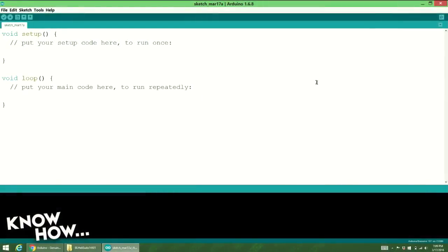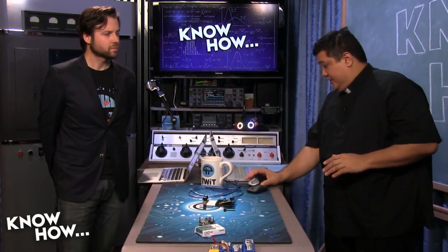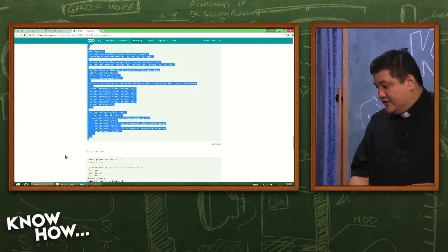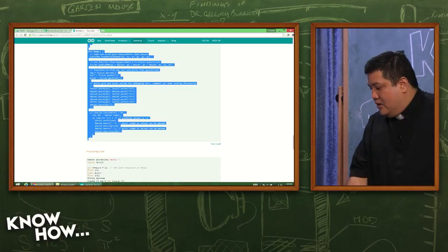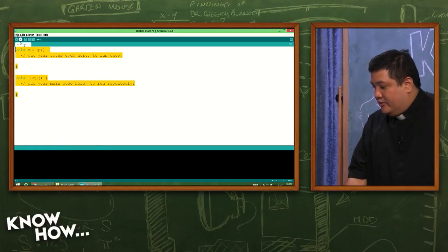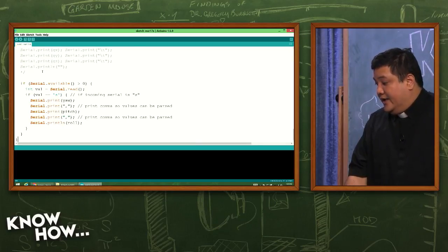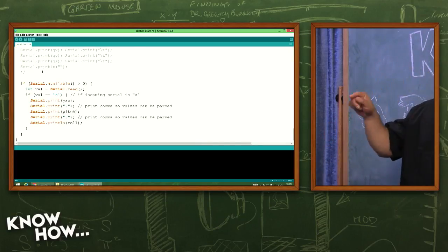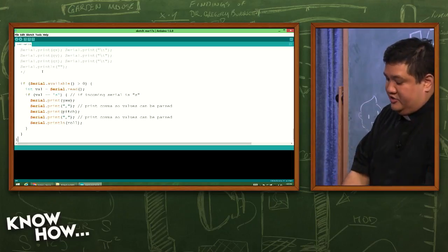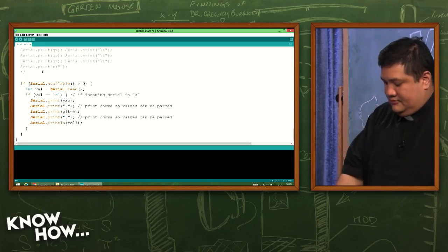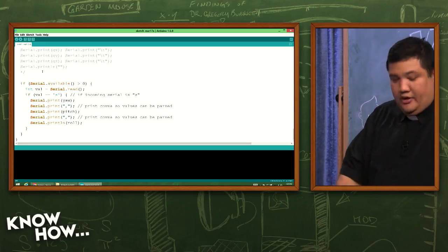What I'm going to do is not do anything special here. I'm going to copy and paste code directly from the Arduino site. Alex, if you go back to my screen, this is the Arduino Genuino screen. I'm just going to copy and paste this entire block. What this is going to do is upload firmware to this new Arduino 101 to tell it to push out its location values to the serial port. So then you can see what information it's logging. Precisely. So here we go.